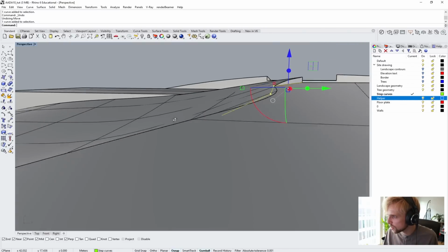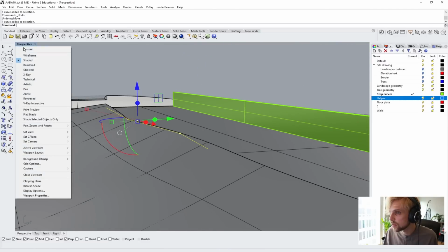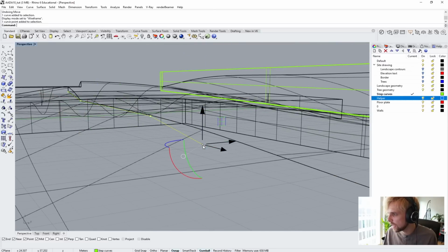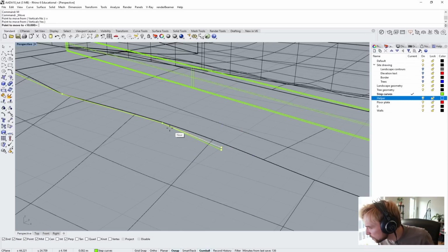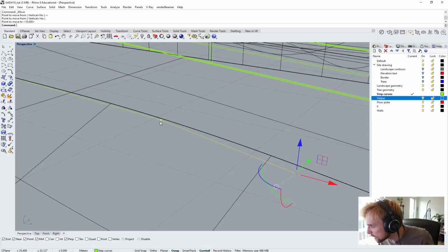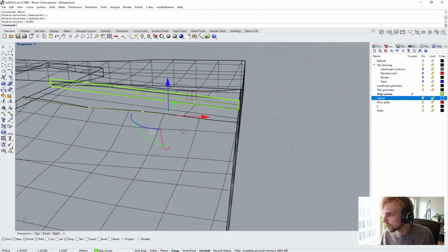So stuff is weird. How do we fix that? Well, we need to flatten this curve out, right? We need its points to be at the same height. So just the one that's going down, I will move, enter, vertical. So V, enter, from this point to same height as this point, right? So I just move it up to the correct position.